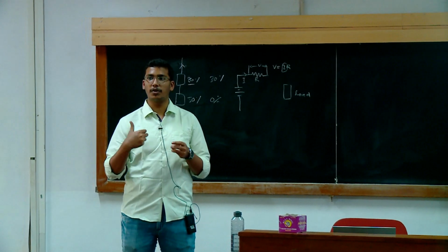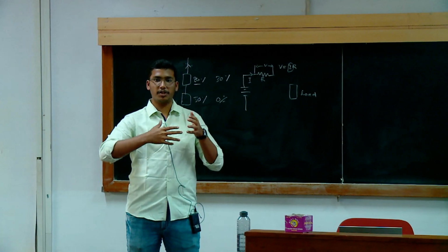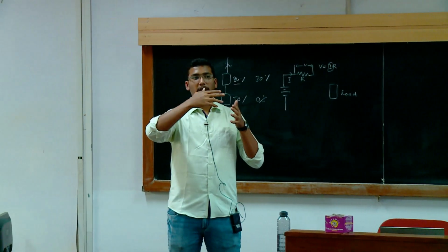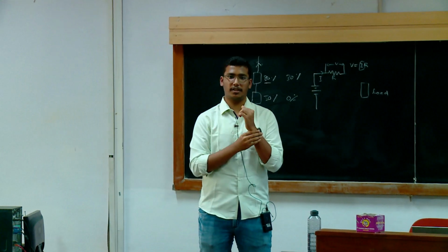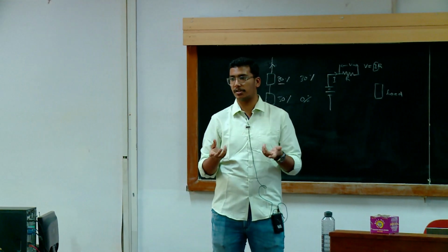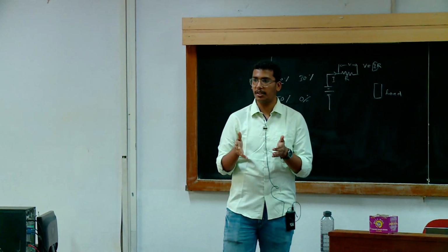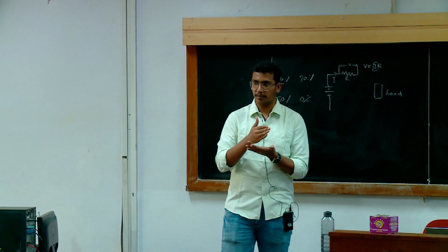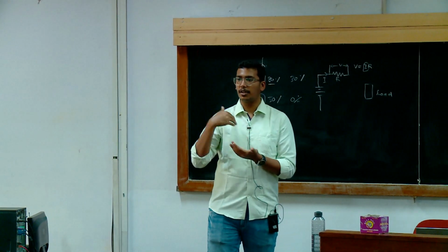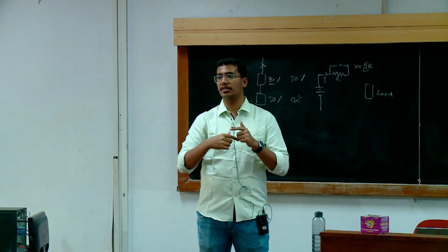Then we may have to put in an advanced BMS with every measurement going on simultaneously, and we have to employ a high grade processor with enough bandwidth and computational capability to perform the measurements and feed the battery balancing algorithm to the balancer circuit.